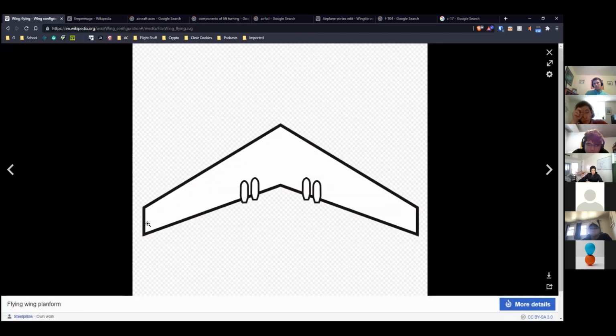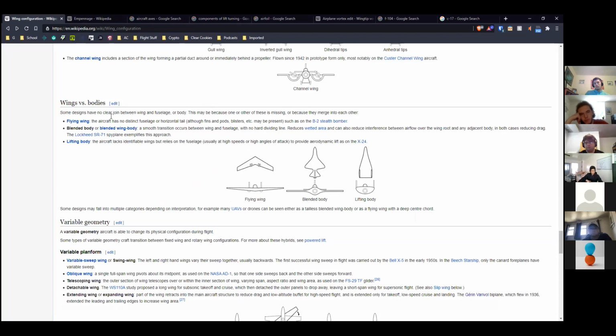Flying wing is one of the tailless designs because you just put elevons way out on the tips. It's kind of harder to design because a lot of the rules from conventional don't apply. But in general, you still need your center of lift to be behind your center of mass. That determines what shapes you can do, because you need enough mass up here and enough lift back here that it balances out the way you want.